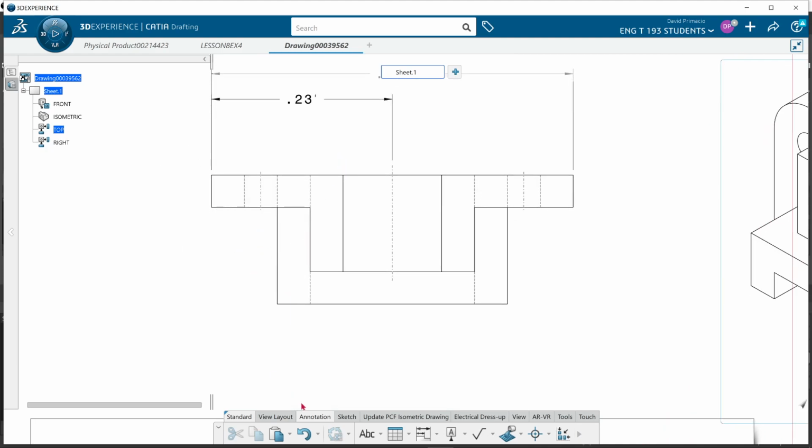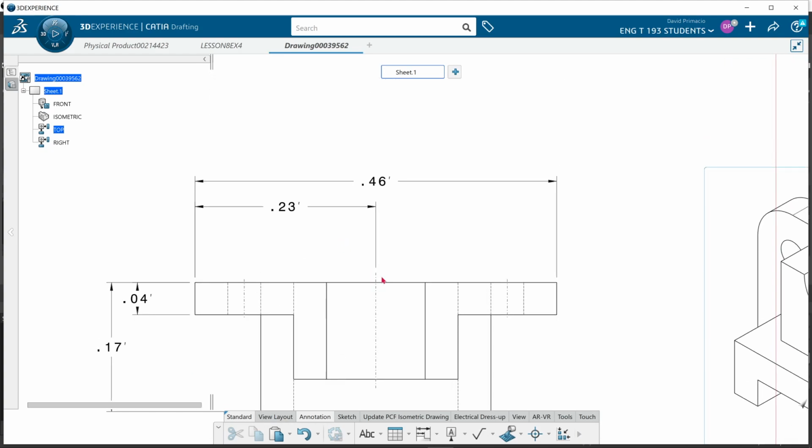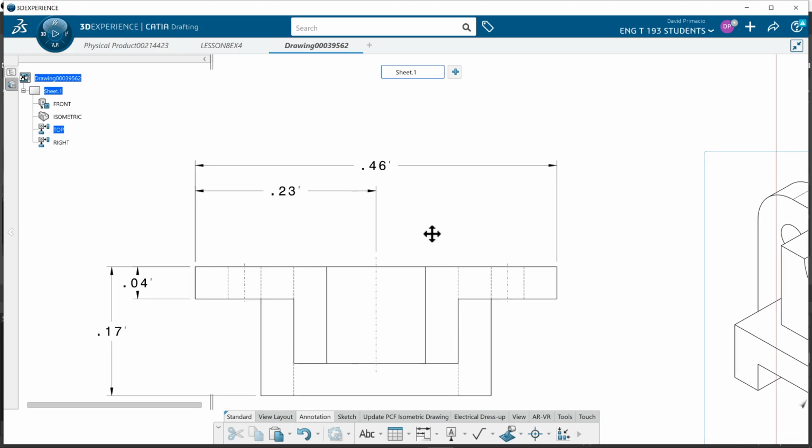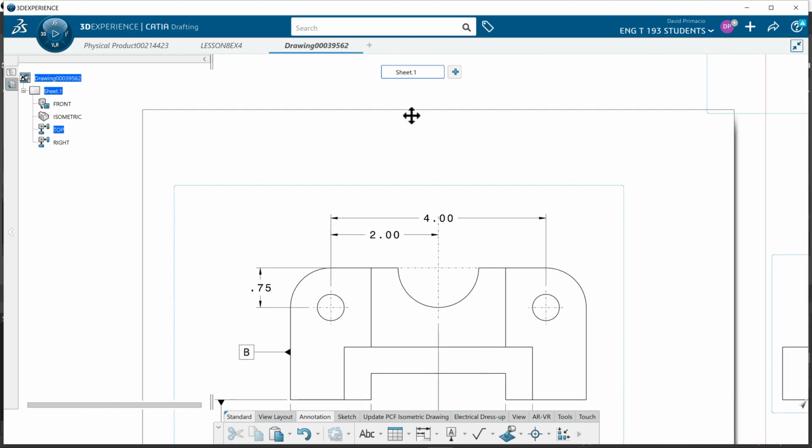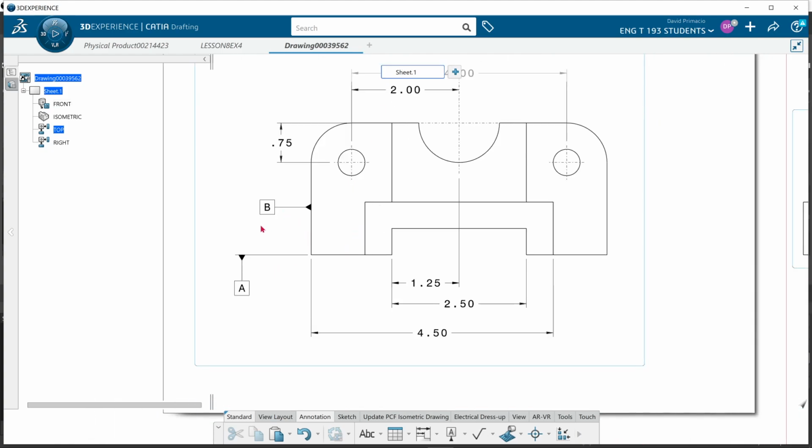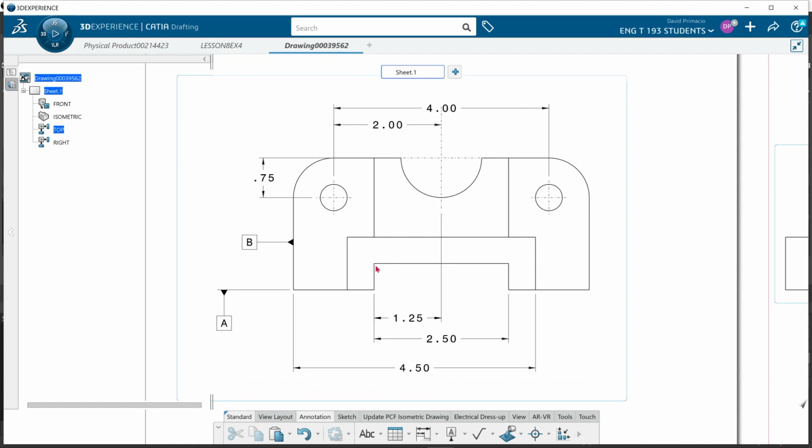This dimension here, going from here to here to here, this is not symmetrical. There's nothing symmetrical going on. So I would dimension from the datum and stack dimension. But this one I'm going from the center over and over, okay? So yes, even though these might be your datums, it's not wrong to dimension from these centers. In fact, that's how you've got to do it to hold symmetry.